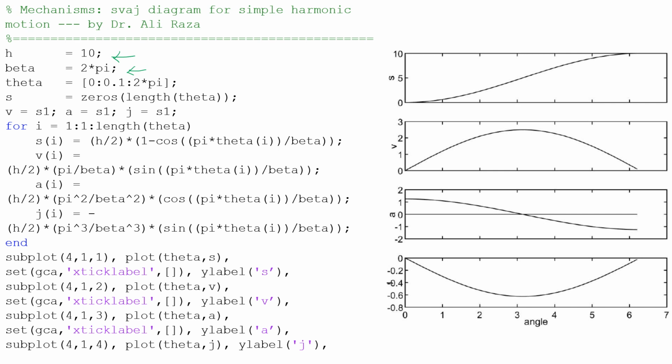And then if omega terms can be incorporated in it, so omega terms can be added and see the behavior of a selected angular velocity added to the cam follower system. So that inference can be incorporated in these expressions as well. So you can see the S expression over here, V, A, and J all written down in a similar fashion, and drawn as well over here,